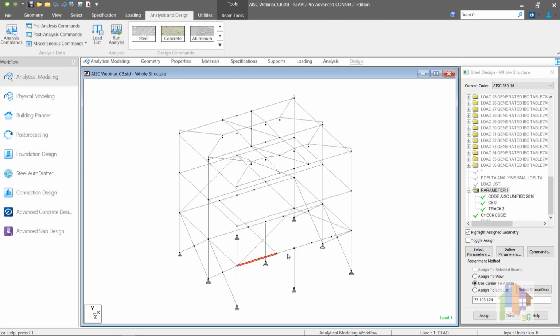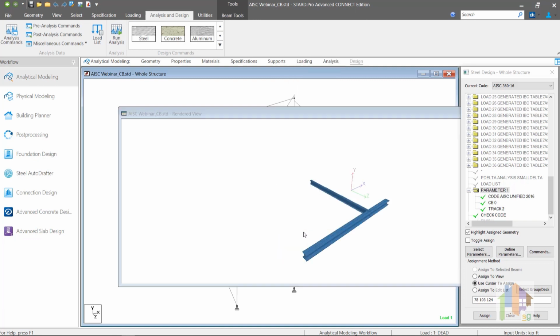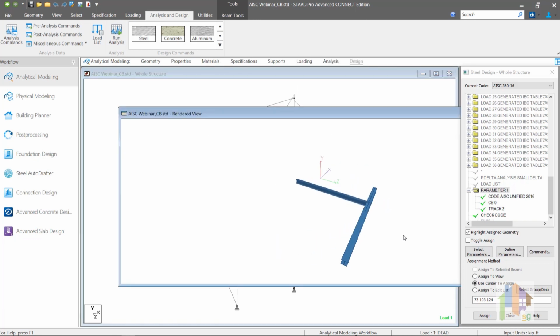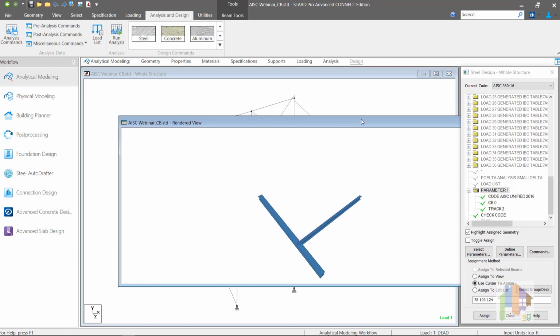Consider these beam members connected between two column members. There is another beam connected at some intermediate node, for which this member is divided in two parts to provide proper connectivity. Now the secondary member provides restraint to lateral movement, and hence the unbraced length for lateral torsional buckling reduces to the distance between the column and the secondary member.